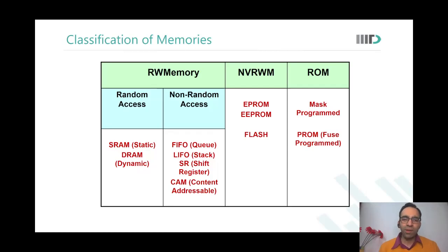So how big a FIFO would you need? Sir, it can be application dependent. Yes, it is largely application dependent. It depends on the kind of variation in frequency, like what are the two different frequencies that you are merging, and also on how frequently you are expected to do this data transfer between two domains. If you are transferring data in every cycle, then it can't really happen that we use a FIFO to take care of it.